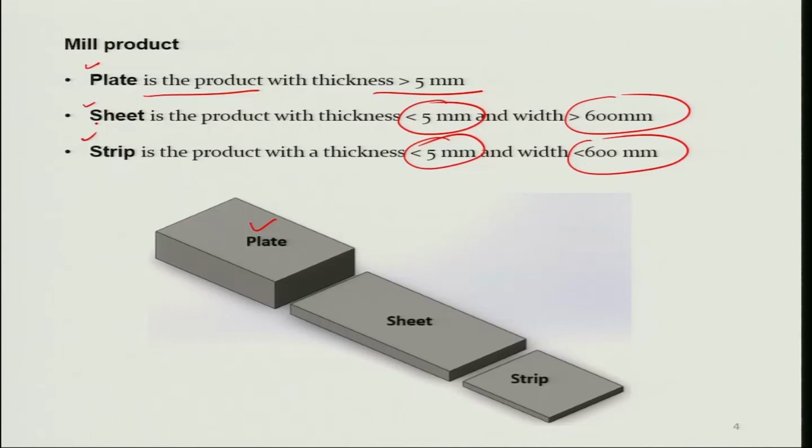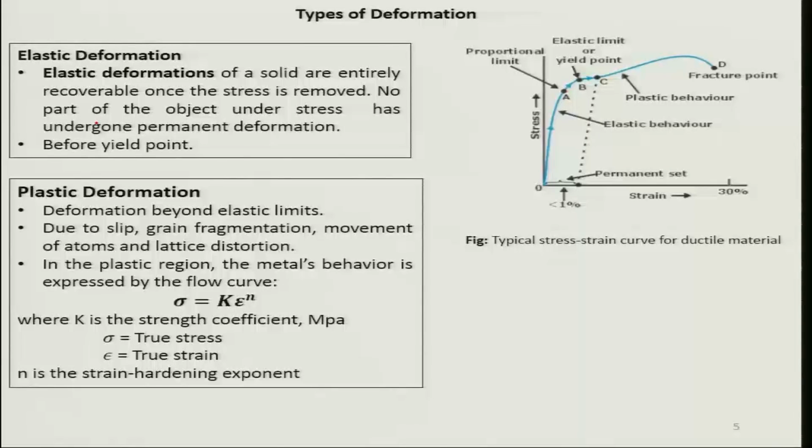So you have the first end process, hot rolling applied to ingots from the casting, creating billets, blooms and slabs, and then you can also further reduce or downsize to plates, sheets and strips. So that's how the various steps can be thought of in the steel industry to produce raw steel, which can be given for the various later machining or assembly processes.